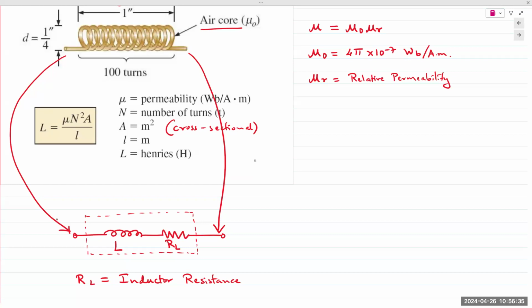It will discharge the energy slowly through itself. And that is represented mathematically and electrically using that resistance. You would say the inductor is charged, it forms a closed loop between its own terminals, and the energy is lost as heat through that resistor. Okay, the same thing happens with the capacitor also. So again, real life inductors will not be able to hold the energy infinitely.